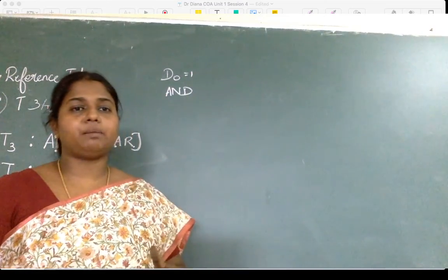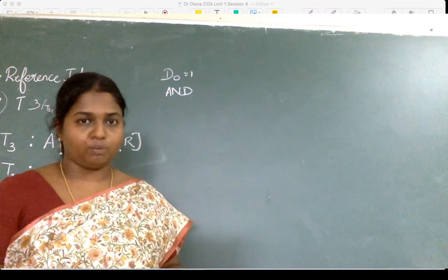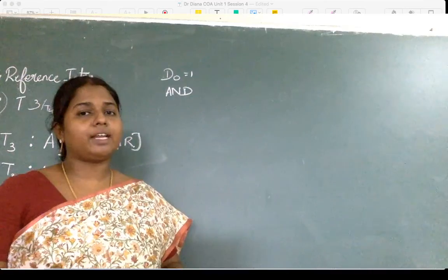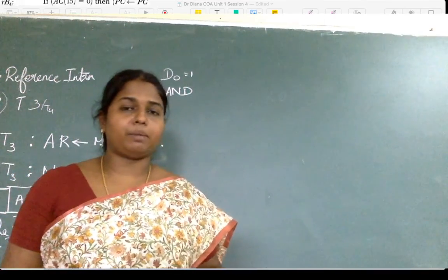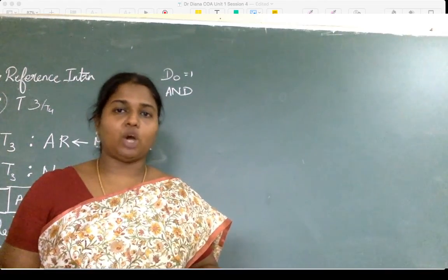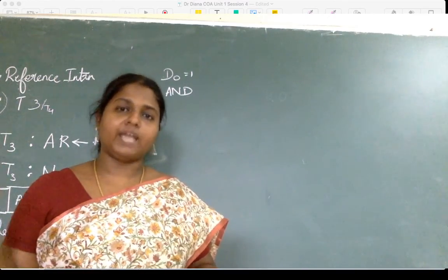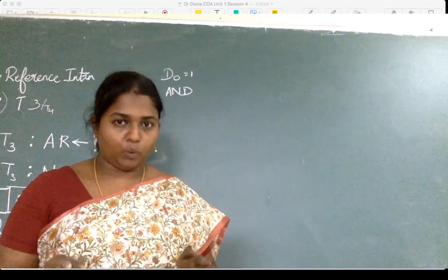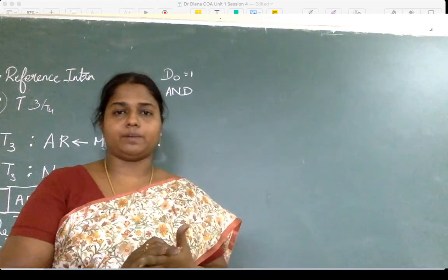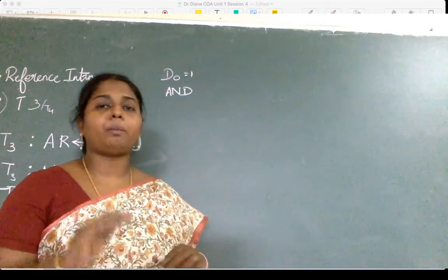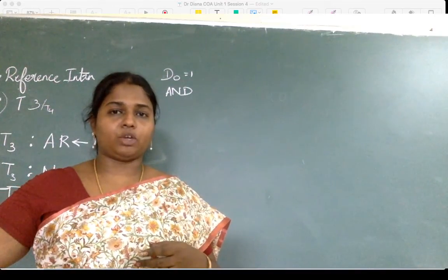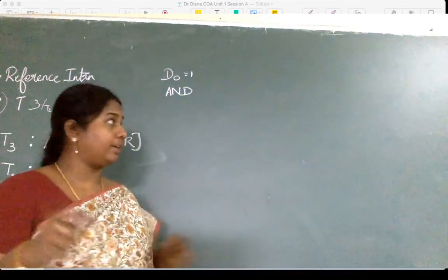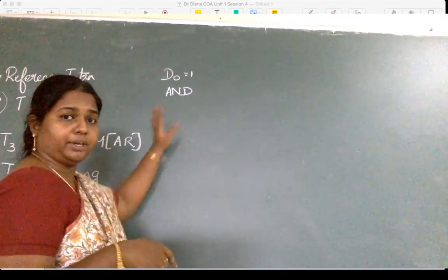The first element by default is the accumulator, and the second element is the content that I read from memory. Because it's a memory reference instruction, one of the operands will be from memory and the other operand, if required, will be in the accumulator. So I am going to perform an AND operation between a memory location's data and the accumulator.